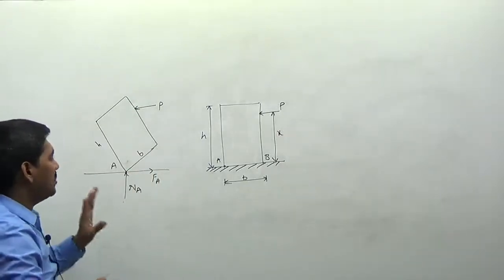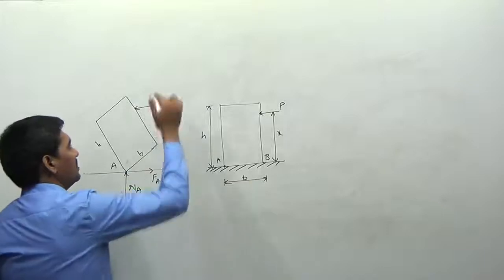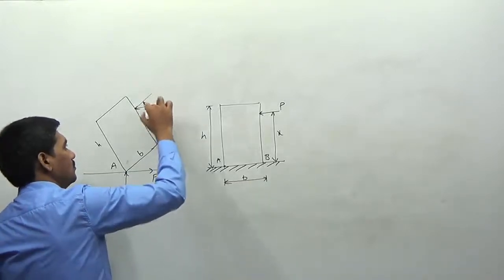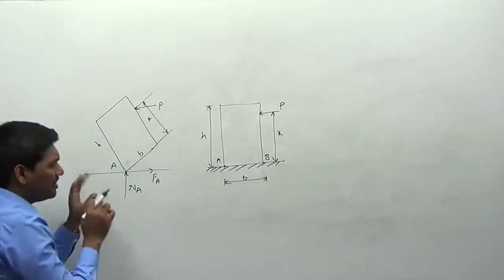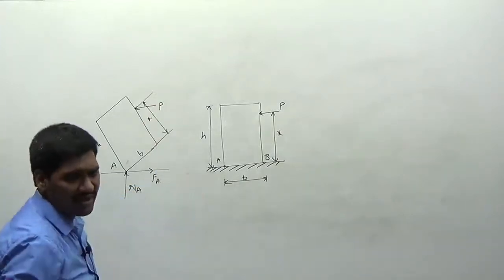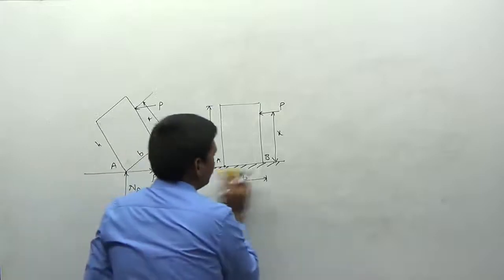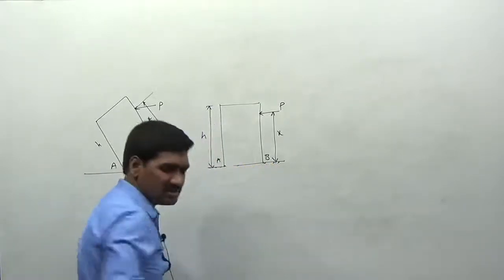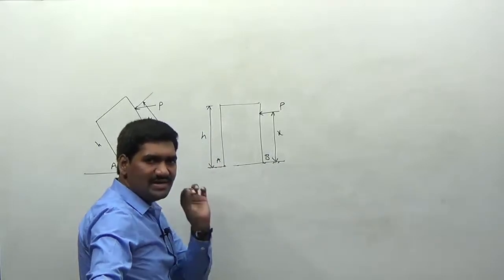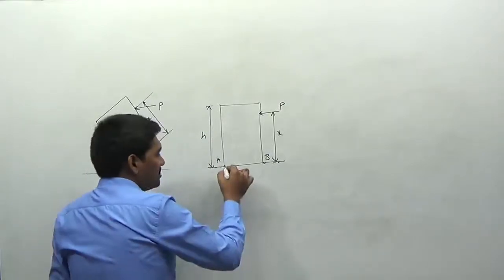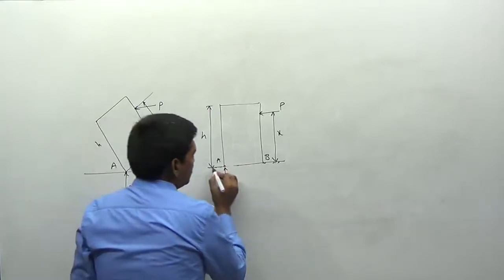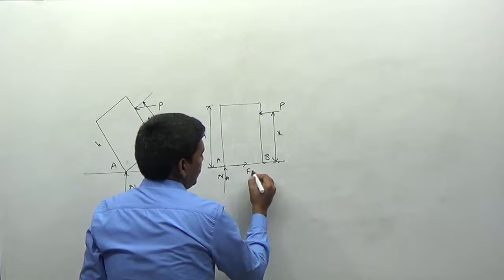Now, how can we determine the value here? I am taking this value equal to X. You can also study the figure from this diagram. I am removing this hatching surface and just providing the normal reaction here. Since only one corner is in contact with the ground, this one is equal to NA, and this is the direction of friction, nothing but the value FA.